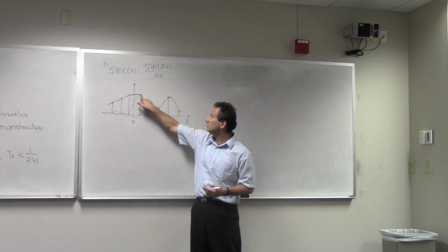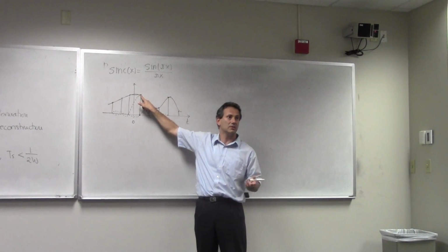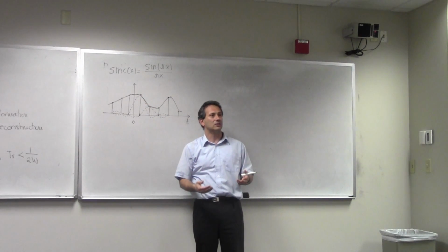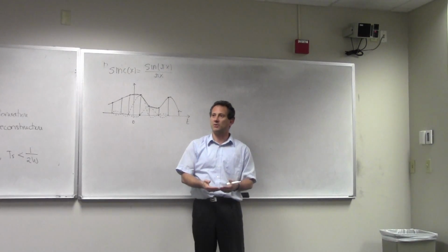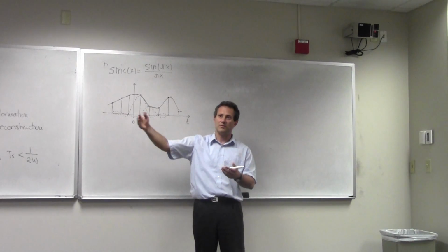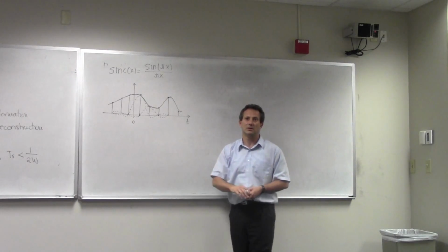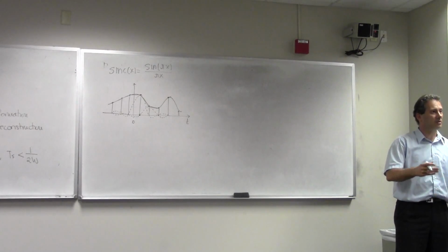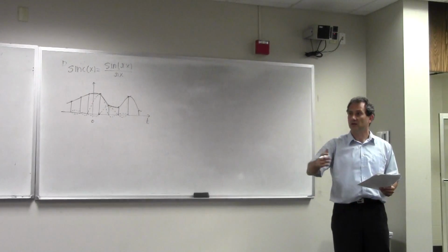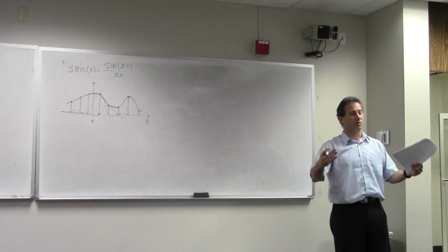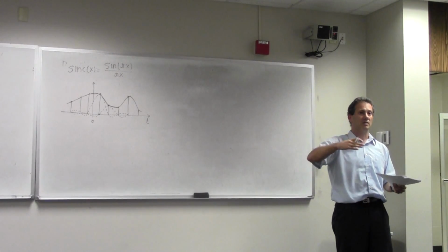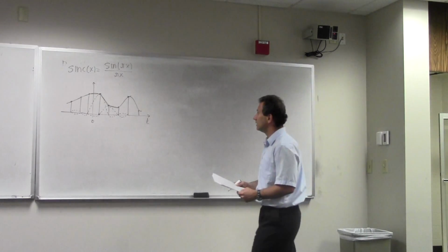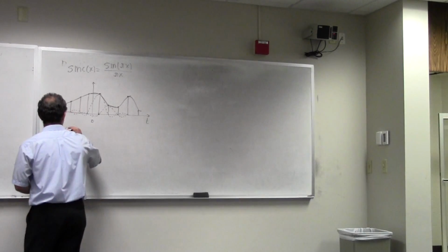As a matter of fact, the value of the sample according to the sampling theorem can be square root of 2. And if we need to represent that in a digital computer, you cannot represent square root of 2 in a computer because it has infinitely many digits after the decimal point. So we need to perform discretization of the signal in both domains. The sampling theorem teaches us how we make a continuous signal discrete along the t-axis. The quantization process tells us how we actually make the signal discrete along the y-axis, the amplitude axis. So let's talk about quantization.